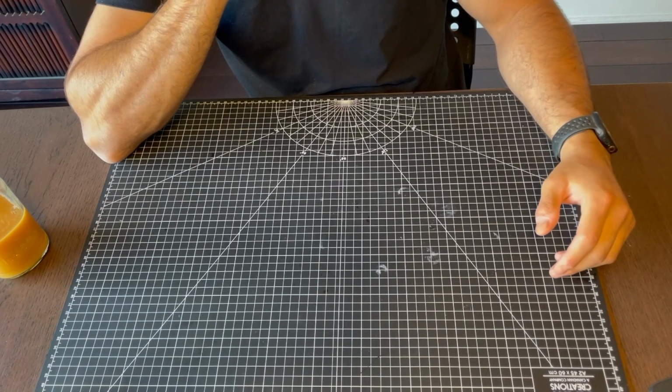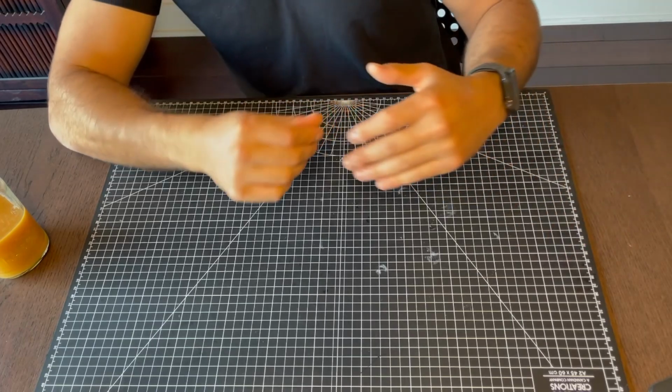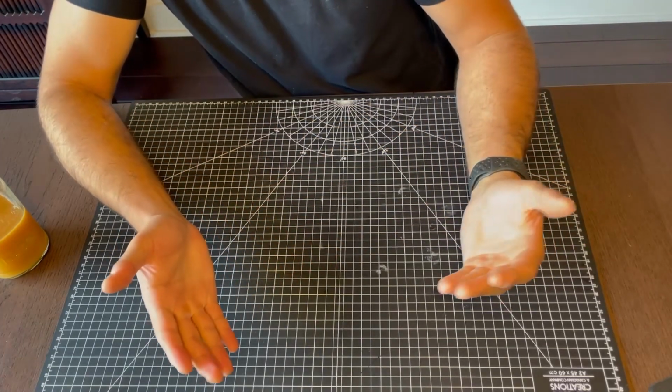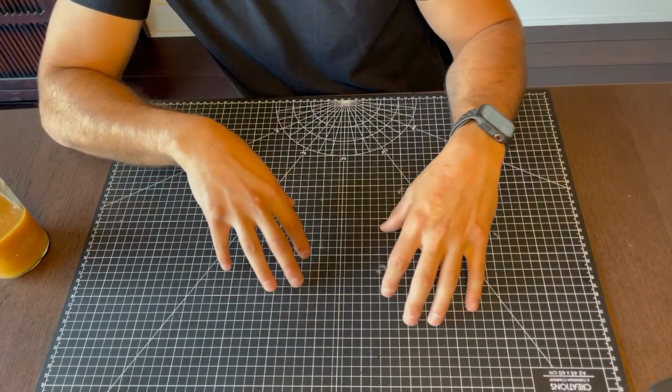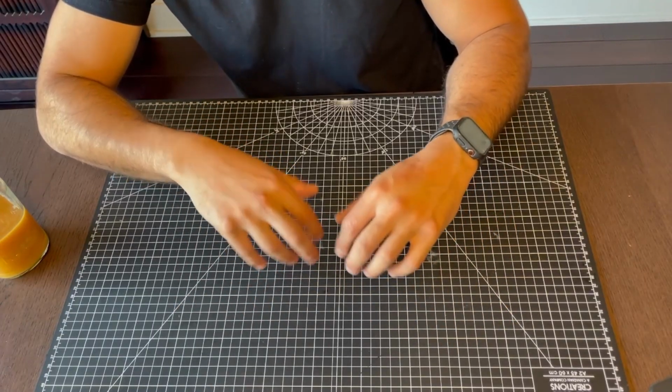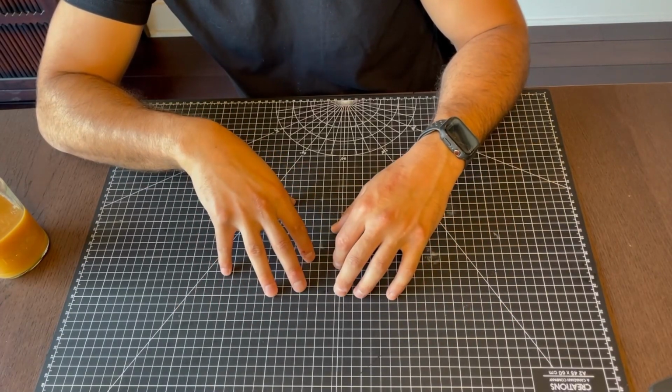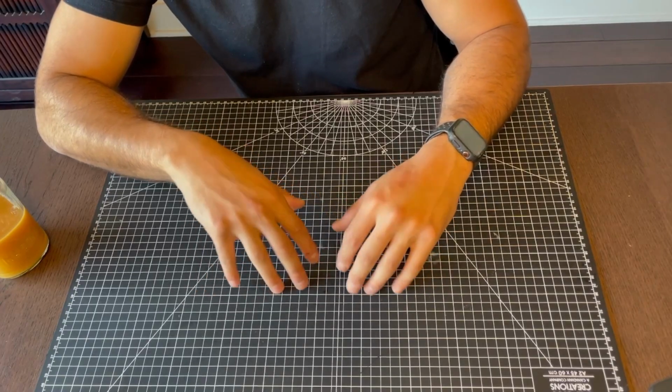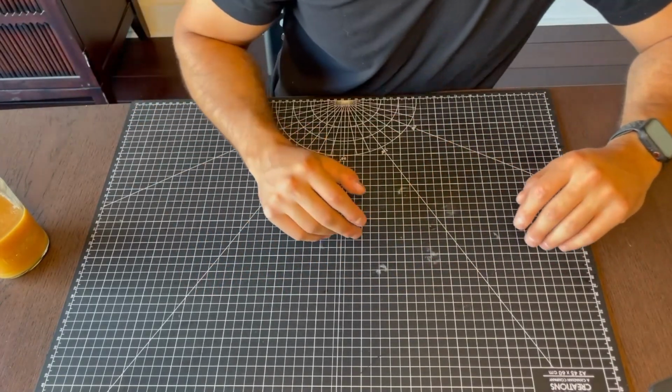After picking the material, which in this case isn't important because I'll explain why later, it's based on actually, I can explain it now. I want to identify the high stress points qualitatively. I just want to see where the material is going to be under a lot of stress. I don't need to know what the numbers are. So the material itself doesn't really matter. Let's put it that way.